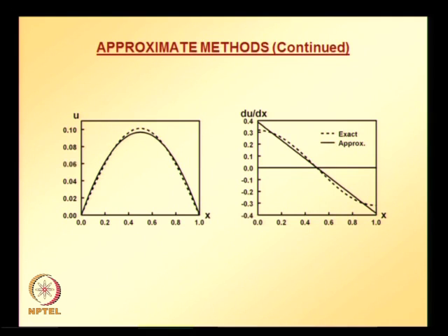So that is why the Galerkin method is superior to the least square weighted residual method and the collocation method. Please note that we put in the same amount of effort. We started with a quadratic trial solution and still got a better solution using the Galerkin method. And if one wants to improve the solution we just obtained using the Galerkin method with a quadratic trial solution, they can do it by selecting a cubic, quartic or quintic polynomial as the trial solution.